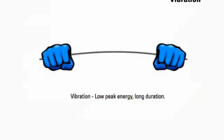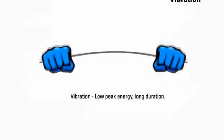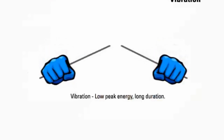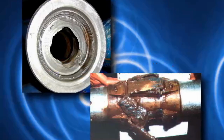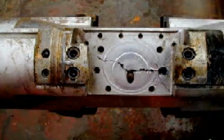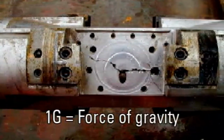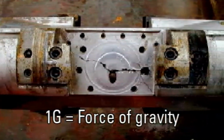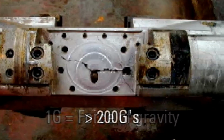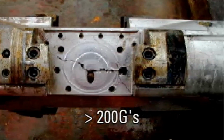Vibrations can result from the shocks. Rapid and continuous vibrations result in fatiguing of the drill string connections to the point of twisting off. This is why many drill string failures are the result of cumulative fatigue due to vibration, and have regular inspection periods. Shocks are measured in G's by an accelerometer. 1 G equals the force of gravity. Shock magnitudes registered via downhole tools can exceed 200 G's.